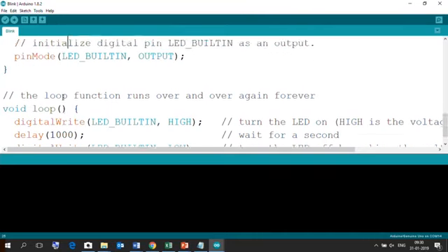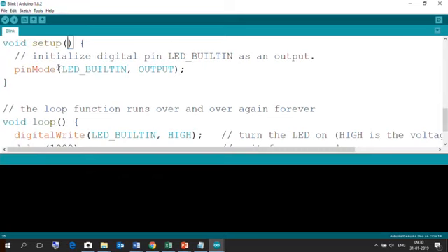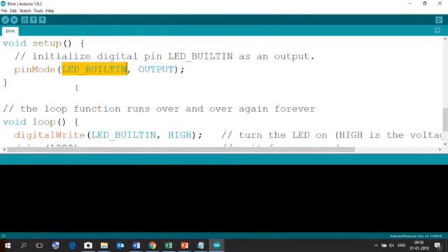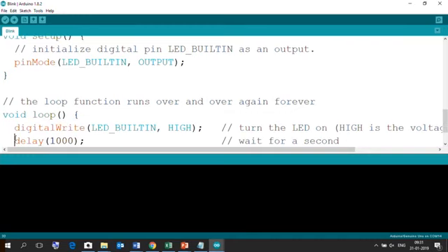Here we have initialized the pin mode for the LED_BUILTIN. So on the same pin number I want to connect the LED. As we already mentioned, LED_BUILTIN is your pin number 13. So I will be connecting that LED one end to pin number 13. The cathode side will go to ground, the other end of the resistor to go to pin number 13, where we are trying to make that LED on with the digitalWrite predefined method available in the Arduino programming construct.